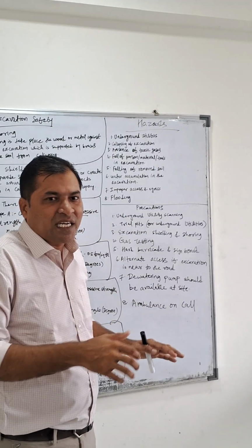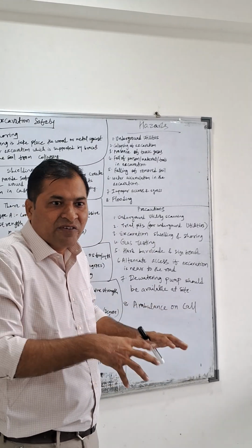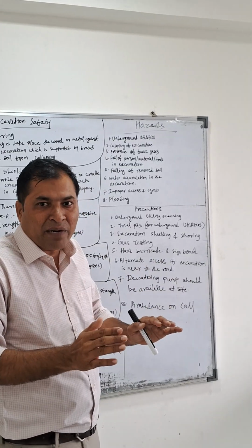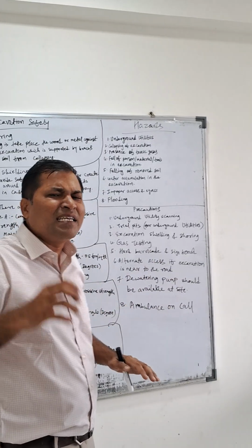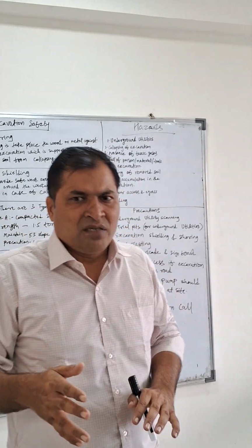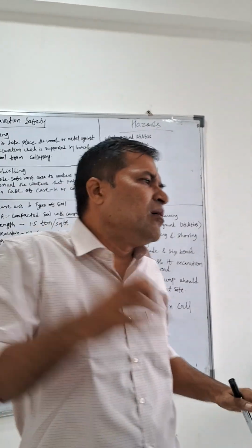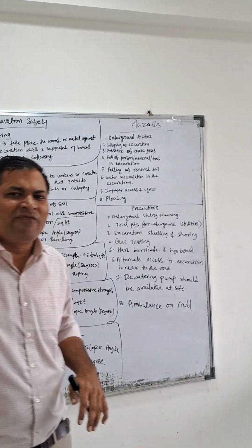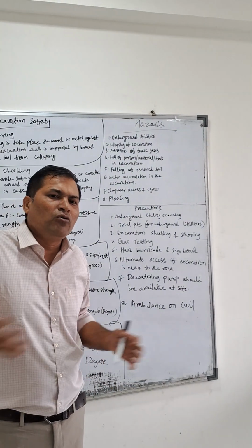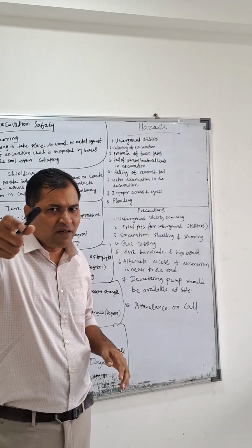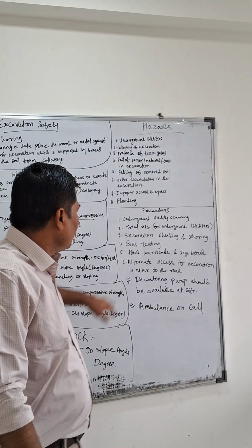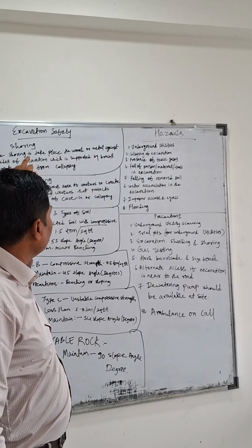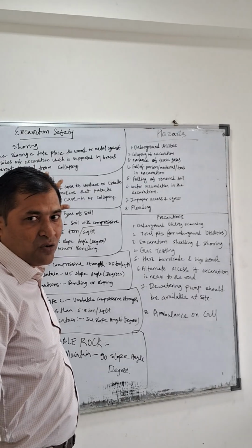Okay, if there is any water accumulation or any other hazard you come across, immediately you can barricade that part. You can cover that part, and you can also go with a mitigation process. Whatever mitigation process you need to apply, you can apply over there. So your workers are working in a safe way, in normal conditions, and you also work normally. That kind of thing is very important. Okay, excavation, shielding and shoring, which I already covered over here.